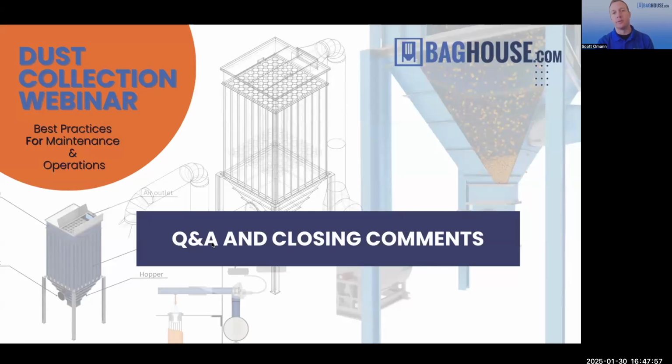Yeah, we don't have a one size fits all approach. There's a couple of different things that we need to keep in mind when we look at our filter media or the fabric type. The first one that we would consider would be the temperature. Do we have a high temperature or a low temperature application?